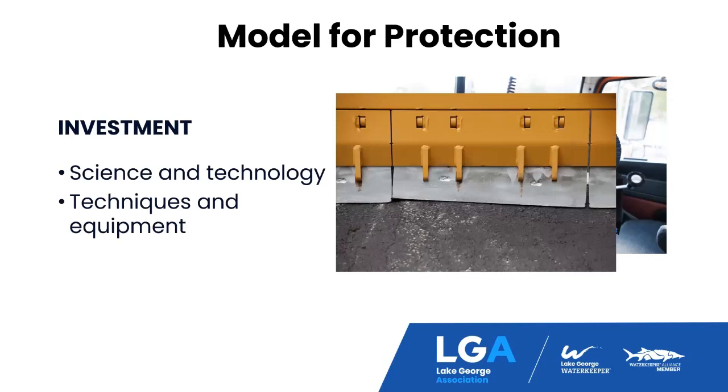The techniques and equipment we're talking about, what operator doesn't want to have better equipment? Through our SALT summits and our partnership with WIT Advisors, we worked with Metal Plus, who brought in the live edge plow. So instead of having a straight metal blade across the bottom, 11 feet long, this had a series of segmented metal blades, which would conform to the road better. And through the data tracking, we were able to document that drivers with the live edge plow used 25 to 40% less salt than when you took that plow away and gave them the other standard plow technology.